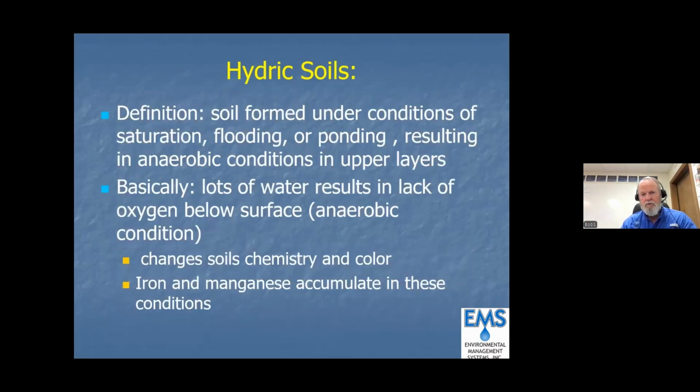Hydric soils, these are also mapped by the Natural Resource Conservation Service, and those same kinds of maps are also available on some county websites where they will identify what's likely to be hydric soils. Again, you're going to be looking at the actual maps, but you have to go to the site and determine what's really there. And just a couple of inches can make a difference between approval and denial on some of these soils.